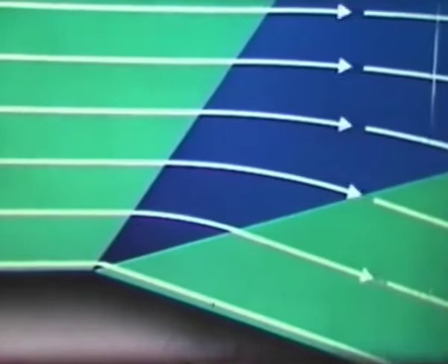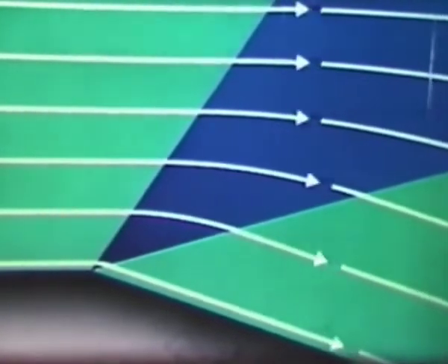Supersonic flow behaves much more smoothly and simply. Boundary layer separation is relatively unimportant. How do these facts about supersonic flow affect the design of actual aircraft? Here's a wing section which would give lift at supersonic speeds, a thin, flat plate.